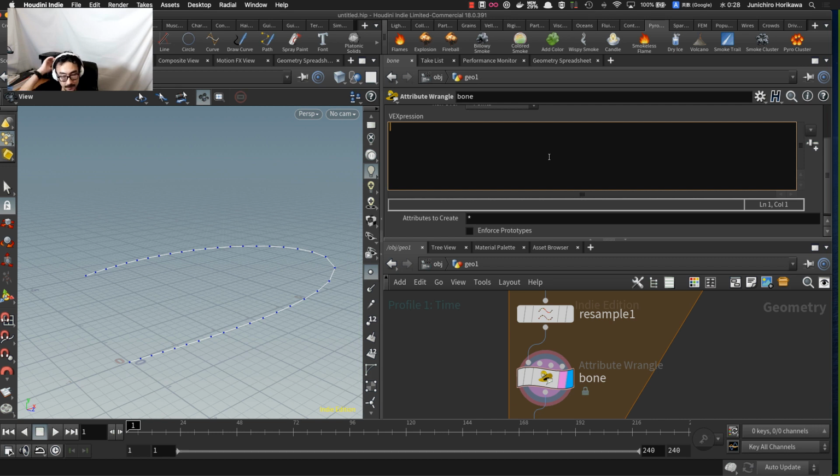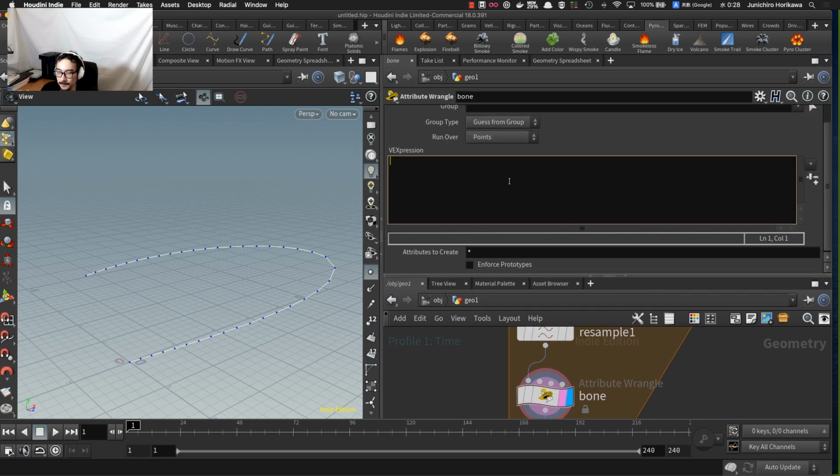First of all, I need some parameters that I want to be able to control. Let's create a number of twisting using this axis, how much it should twist, as an integer, so that the integer will be multiplied with 2π, so that the twisting will be looped within this whole curve. So how do I name this? Twist num.